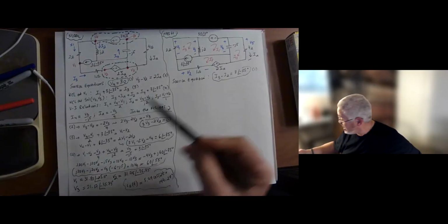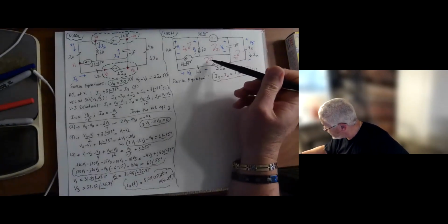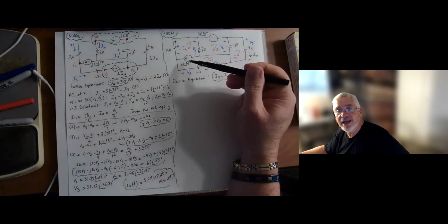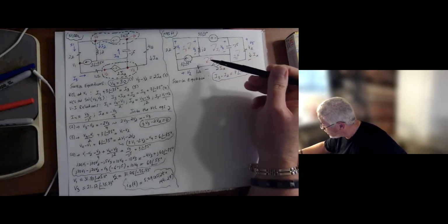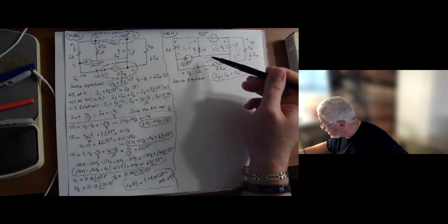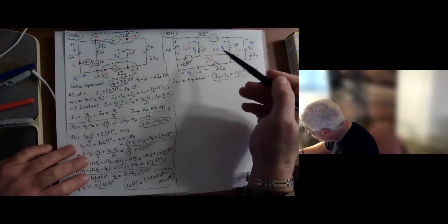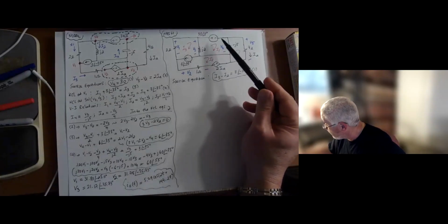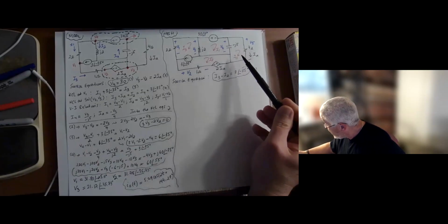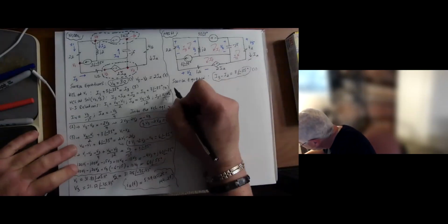The next thing, essentially, I have to note that this current source is between two meshes, mesh I2 and mesh I3. This is the case where we're going to need to do a KVL about the supermesh between mesh I3 and mesh I2. But before we do that here, we have what I would call regular meshes. What do I call a regular mesh? A mesh without a current source. Mesh I1 is a mesh without a current source, if you look around. Mesh IA is a mesh without a current source. So we have two regular meshes. So let's do KVL about them.